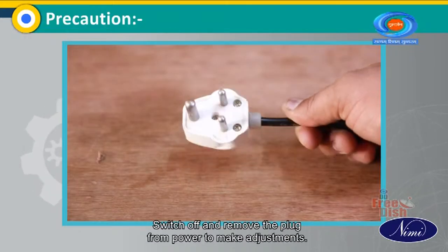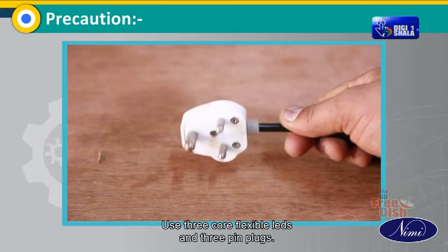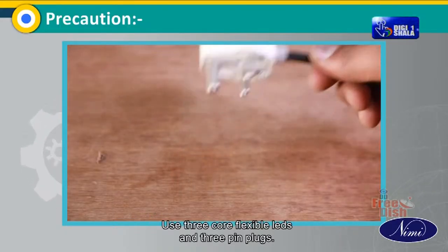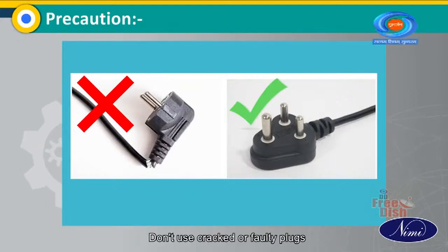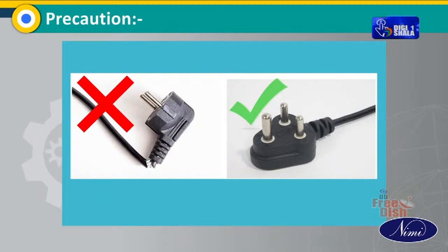Switch off and remove the plug from power to make adjustments. Use 3 core flexible leads and 3-pin plugs. Don't use cracked or faulty plugs which may cause leakage of current, which is very dangerous.